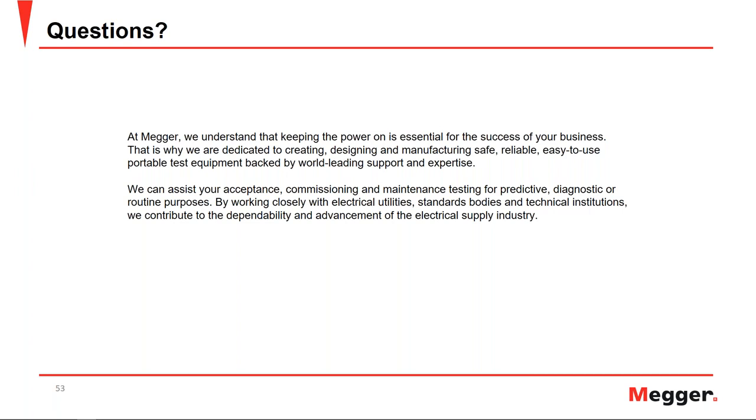Coming back to the question, what is the probable reason for getting a negative tan delta value? If you go back and look at the theory of power factor testing, the best power factor that you can hope for is 0. So anytime you get a negative power factor value, it's an indication that something is not right.